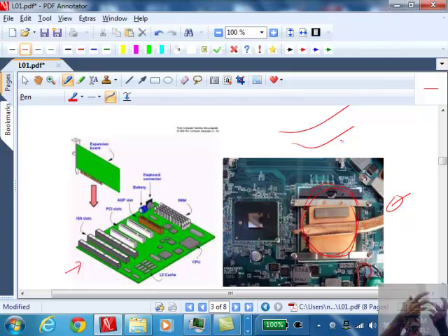So all I get from a thermocouple is a voltage signal. And that voltage signal is amplified, converted, and sent to the digital control room. And that is converted into a temperature, and that is displayed on the monitor. So there are conversions of signal all along from the distillation column into what is displayed in here. So we need to know how these conversions take place. How are these numbers represented in the various units? Okay, that's one of the things that we are going to do today.